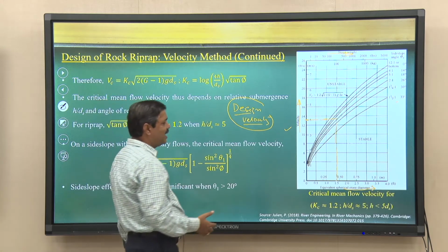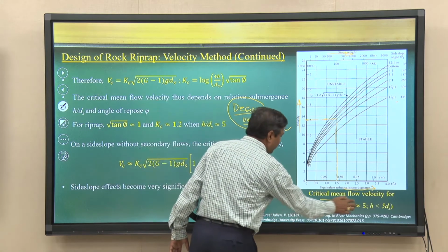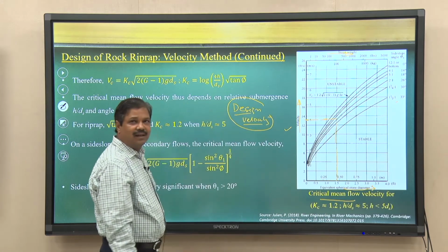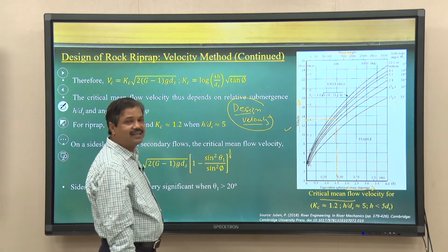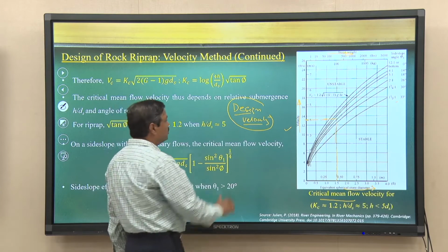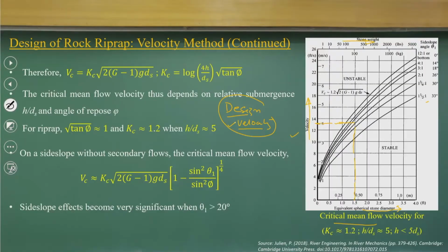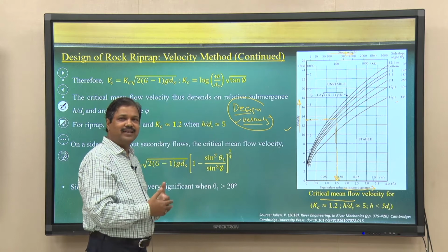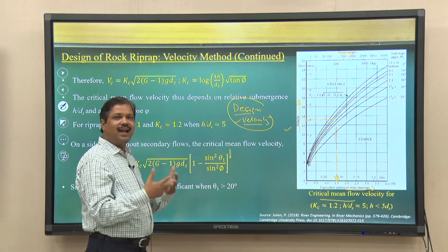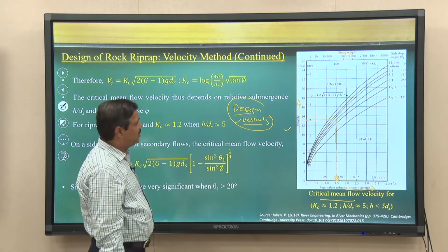Look at this design chart prepared by the US Army Corps of Engineers, which gives us a very interesting figure: if I know the design velocity, I can compute the D50, or representative value, to obtain the riprap size. We also follow guidelines on what the gradation should be and what the packing of these materials should be.